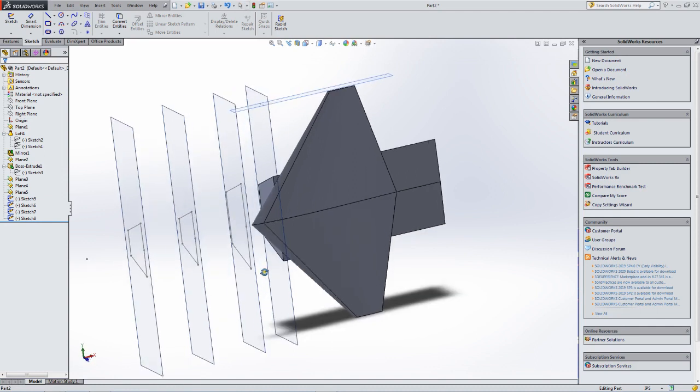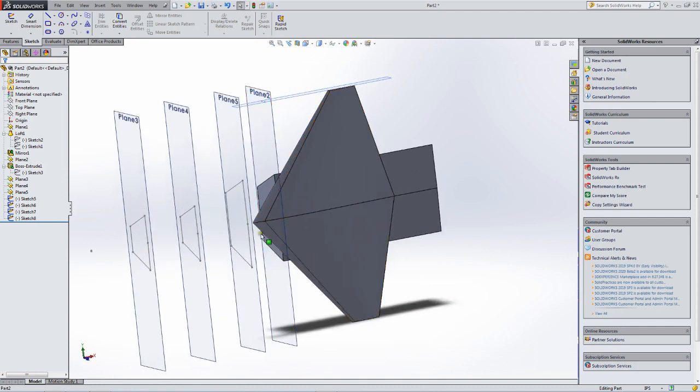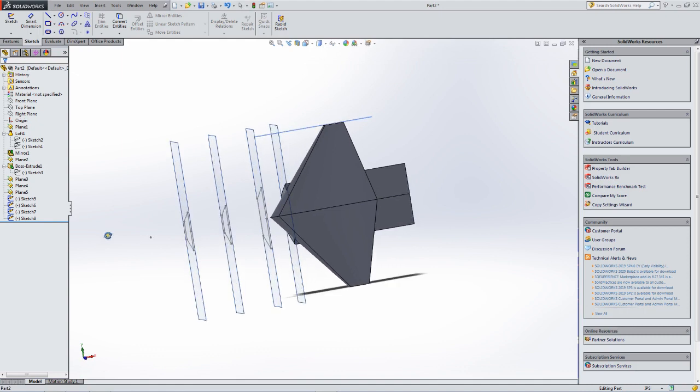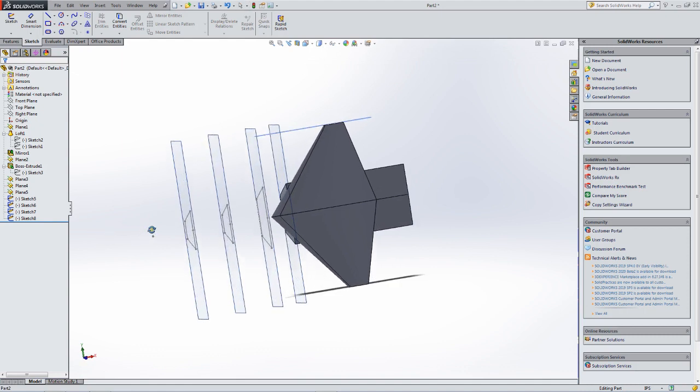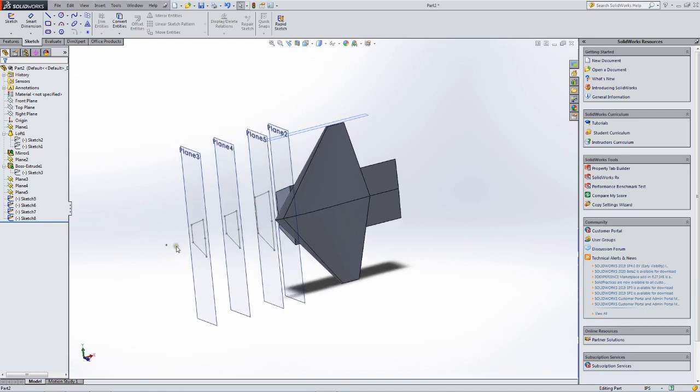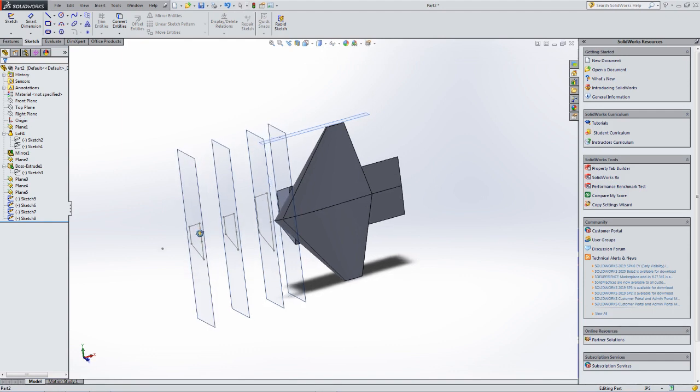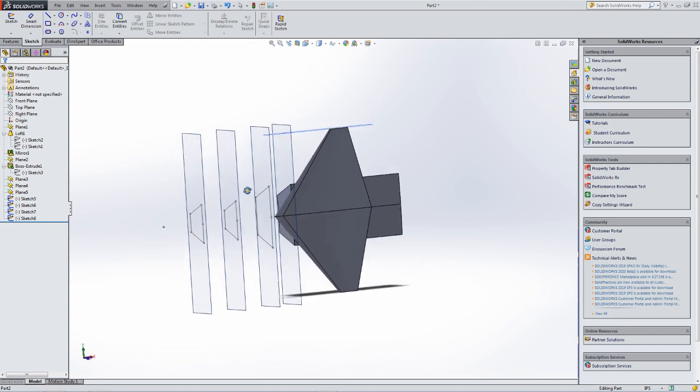We're going to loft from this cross section to this cross section, and then down to these guys and into that point. So that's what the loft is going to try to do. We'll see if it can do it. There's a lot to be said in a lot of cases to loft just one section at a time. But just to show you what can be done, I'm going to loft it all in one piece. So let's try.